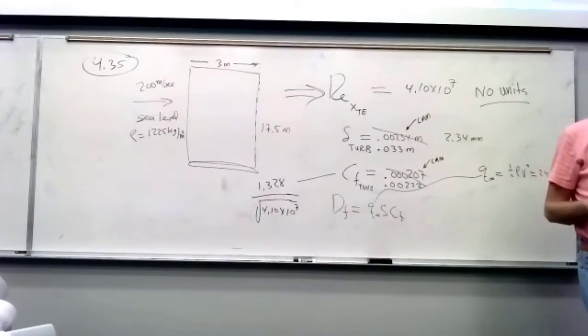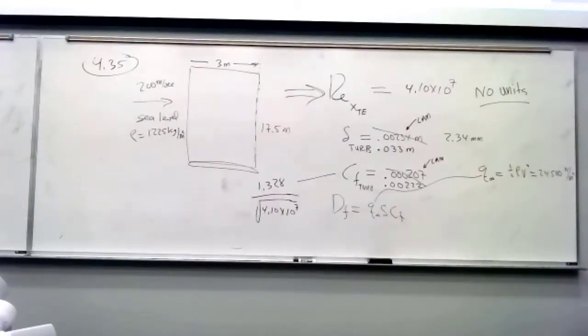So you can see why there's a lot of work to develop airfoils that maintain the laminar boundary layer all the way down the wing. Then they discovered that it had issues with stall, so they tailor the point where the boundary layer trips so that most of the airfoil stays laminar, but when you get down to the separation region, they trip it to turbulent to prevent the slow separation.